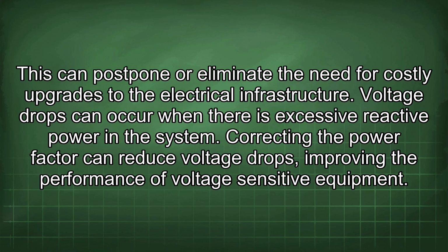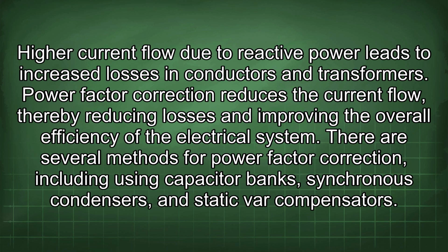Correcting the power factor can reduce voltage drops, improving the performance of voltage-sensitive equipment. Higher current flow due to reactive power leads to increased losses in conductors and transformers. Power factor correction reduces the current flow, thereby reducing losses and improving the overall efficiency of the electrical system.